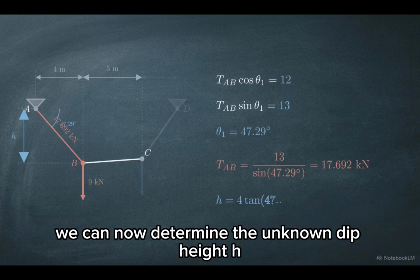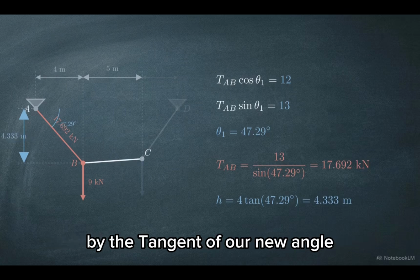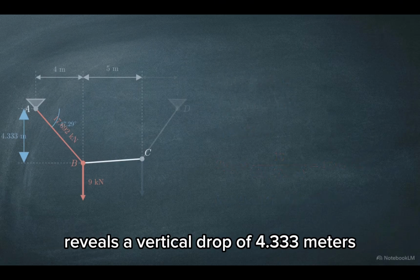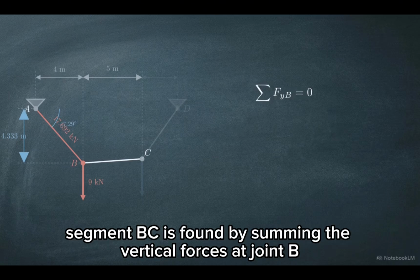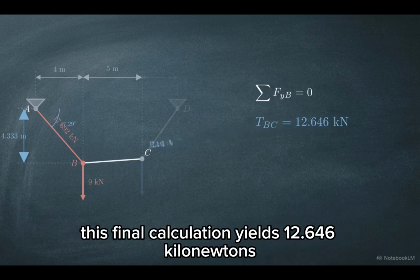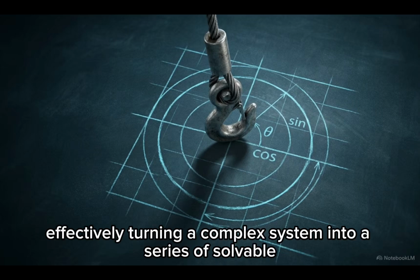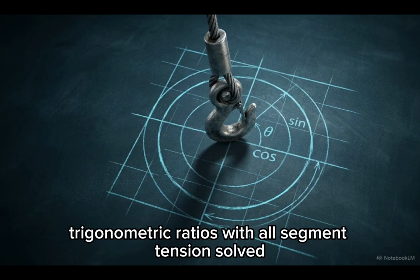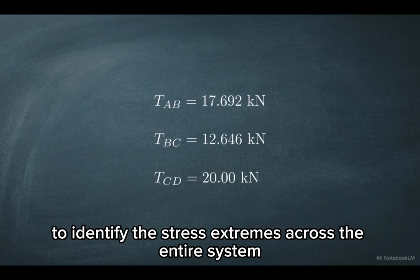We can now determine the unknown dip height, H. Multiplying the 4-meter horizontal distance by the tangent of our new angle reveals a vertical drop of 4.333 meters. Our final unknown tension, segment BC, is found by summing the vertical forces at joint B. This final calculation yields 12.646 kilonewtons. Dismembering the structure allowed us to expose those internal unknowns, effectively turning a complex system into a series of solvable trigonometric ratios.